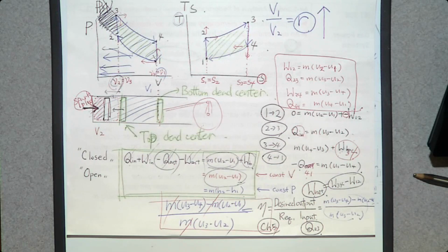That is diesel engine. So in diesel engine, we have only air during the compression process. When it reaches the top dead center, then we inject fuel. Then due to high pressure, high temperature, the fuel is going to self-ignite. That's how we produce power. Okay?